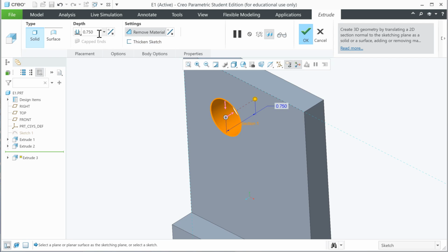Okay, now we could set it to go a half inch deep, which we know is the thickness of this plate. But there's something better. There's something called design intent. And again, Creo is the grandfather, back in the Pro E days, as they call it, of this whole idea of design intent: a plan on how you want to model this so that it's easily editable, so you can edit things, as well as they update automatically in some cases, where you don't have to go back and change things that you might forget about. I.e., change always occurs in design.